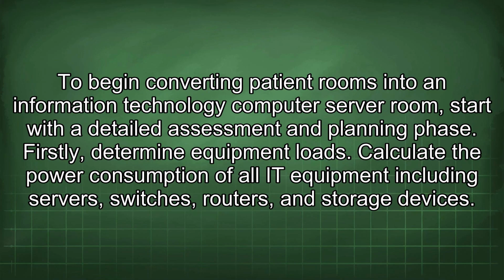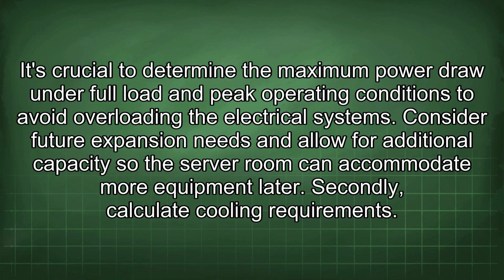To begin converting patient rooms into an information technology computer server room, start with a detailed assessment and planning phase. Firstly, determine equipment loads. Calculate the power consumption of all IT equipment including servers, switches, routers, and storage devices. It's crucial to determine the maximum power draw under full load and peak operating conditions to avoid overloading the electrical systems. Consider future expansion needs and allow for additional capacity so the server room can accommodate more equipment later.